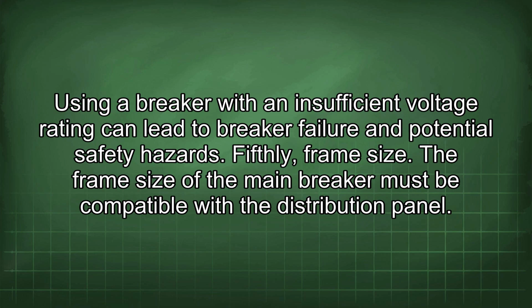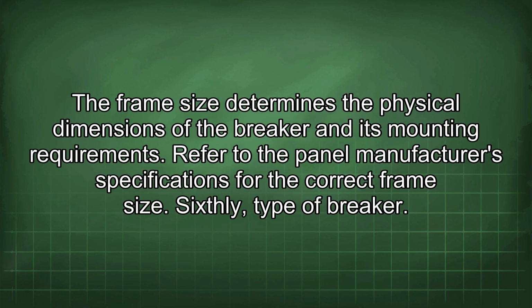Fifthly, frame size. The frame size of the main breaker must be compatible with the distribution panel. The frame size determines the physical dimensions of the breaker and its mounting requirements. Refer to the panel manufacturer's specifications for the correct frame size.